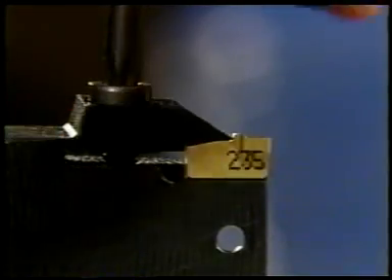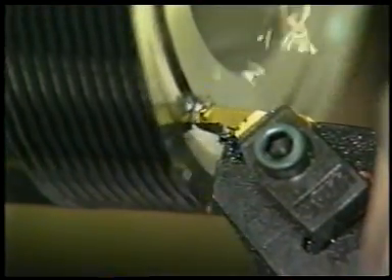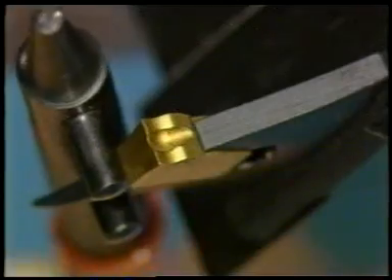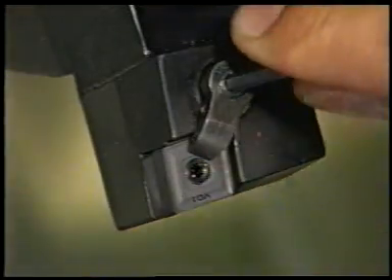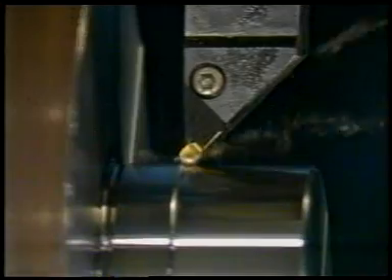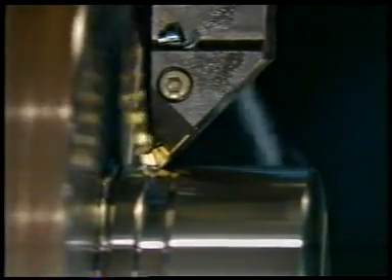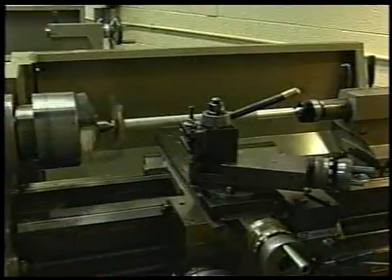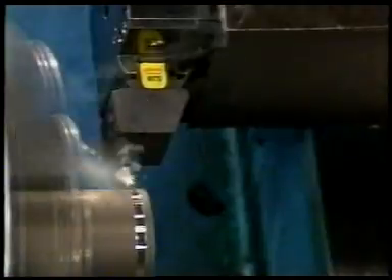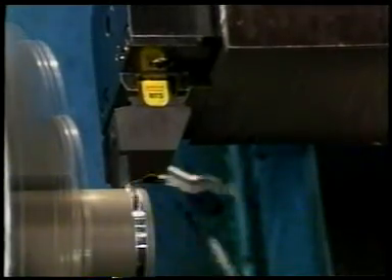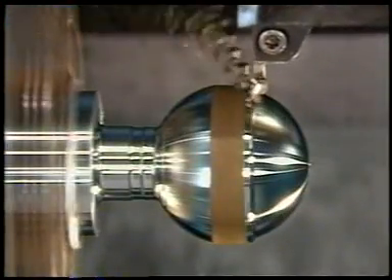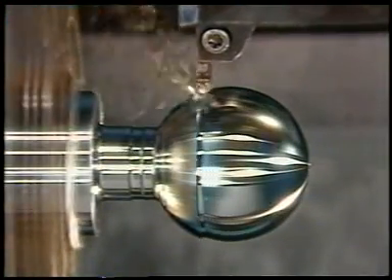Tool makers have clamping systems for their various insert families. Roughing and finishing tools may have different clamping mechanisms or clamp configurations. The size and type of tool holder is determined by the turning operation, the feed direction, the size of the cuts, the machine tool design, the need for accessibility, and sometimes the shape of the workpiece, if, for example, contour turning is involved.